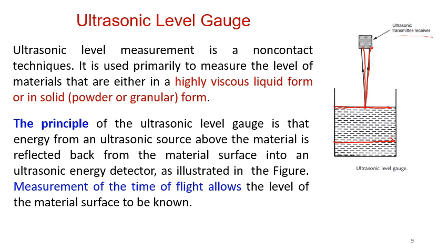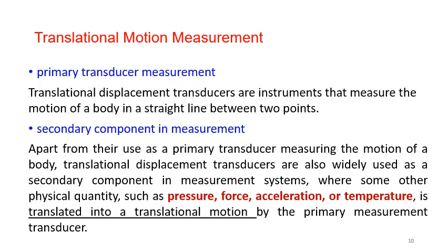So as the liquid level gets higher, of course, the time taken for the signal to transmit and reflect is going to be shorter. That's how we can use the ultrasonic level gauge to measure the level of the liquid.